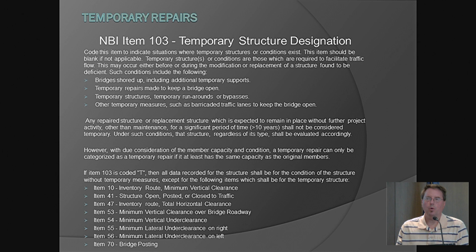And then we generally in the office will look at anything that goes past 10 years. If we've been calling it a temporary repair and it's been in place for 10 years and there's still no plan for anything to be done to change that, it's probably going to be changed over to a permanent repair, unless the county or the bridge owner has requested that it is kept as a temporary.